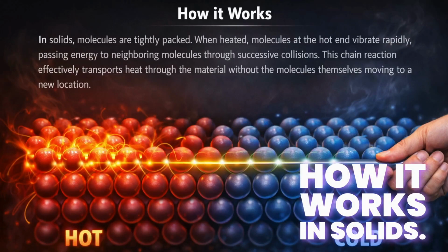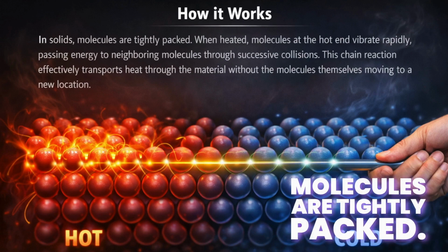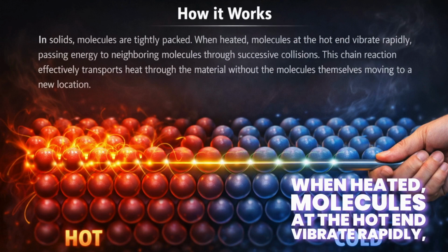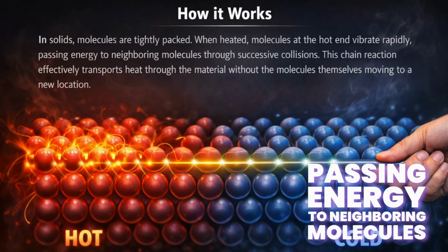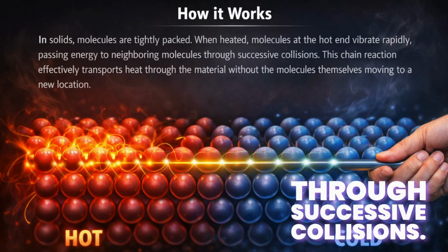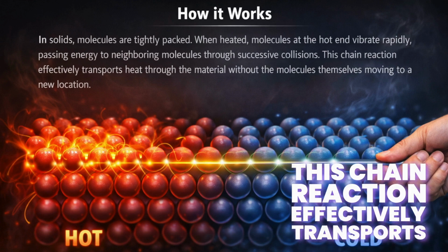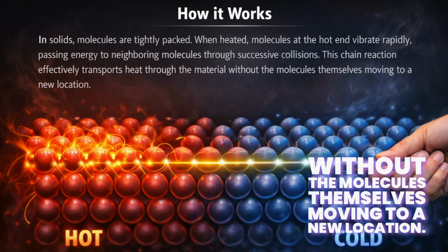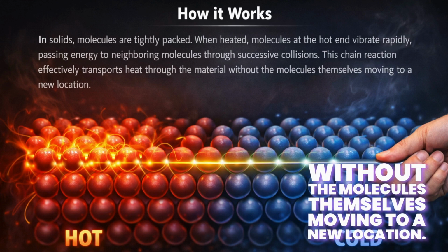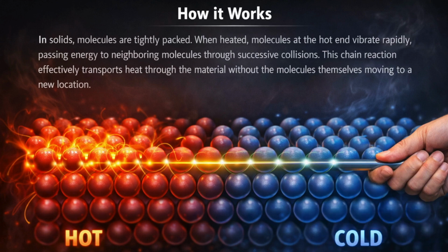How it works. In solids, molecules are tightly packed. When heated, molecules at the hot end vibrate rapidly, passing energy to neighboring molecules through successive collisions. This chain reaction effectively transports heat through the material without the molecules themselves moving to a new location.